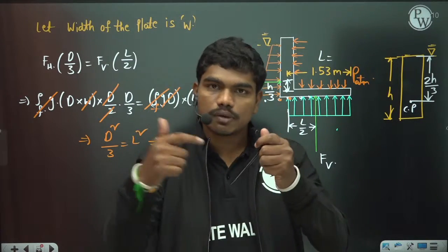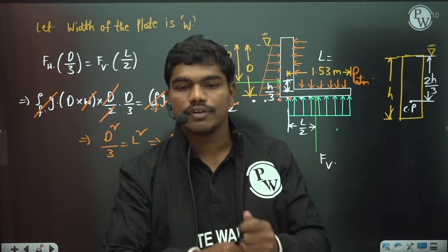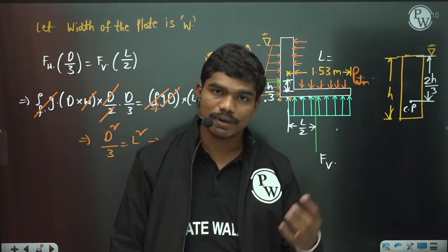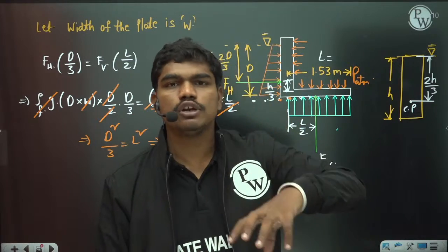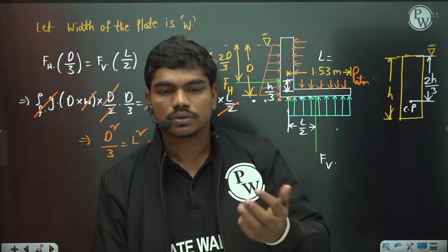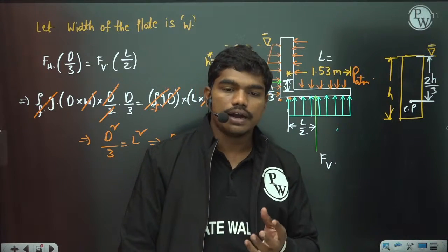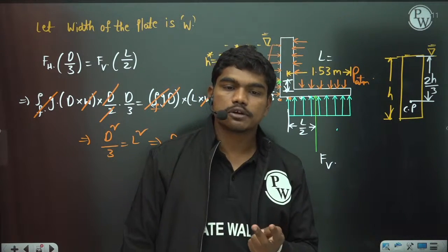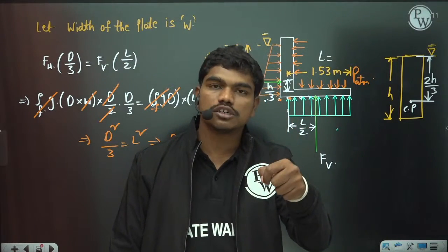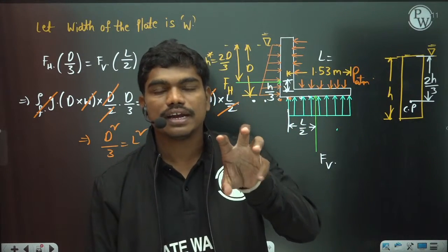You remember, the center of the plate is applied with a force F. This is also a plane surface kind of question. We have dealt with a lot of buoyancy questions, in case of fully submerged and partially submerged, and we calculated metacentric heights. So generally these are the types of questions, and two very common points I would like to tell you. In case of completely submerged bodies, the center of gravity should lie below the center of buoyancy for the body to be in a stable condition.